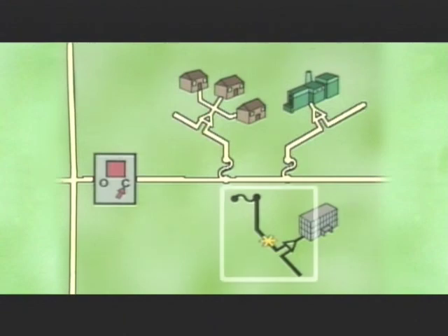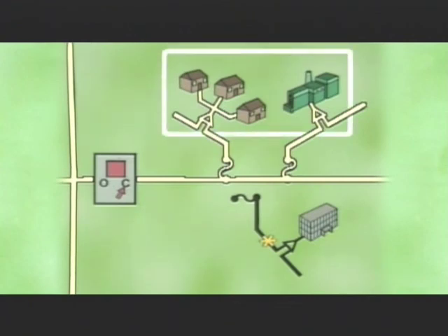When the fuse opens, the faulted lateral is isolated from the distribution system. The circuit breaker will then open and close. When the breaker closes, service will be restored to all parts of the system except the faulted lateral. This process is known as sectionalizing, and it provides protection to the distribution system and its components against damage due to faults. It also protects the majority of customers serviced by the system against outages.